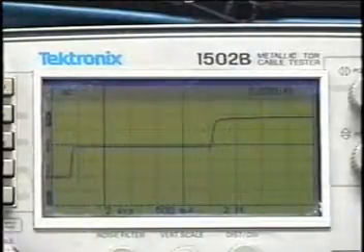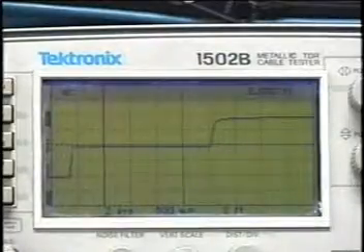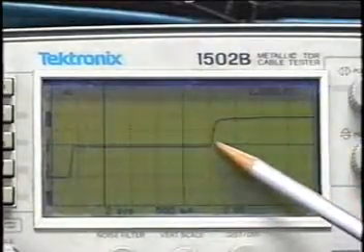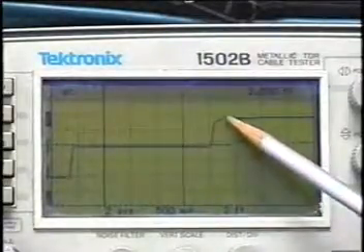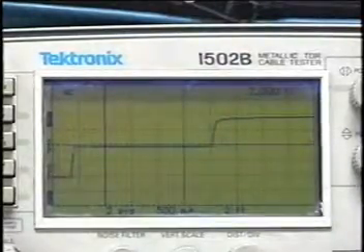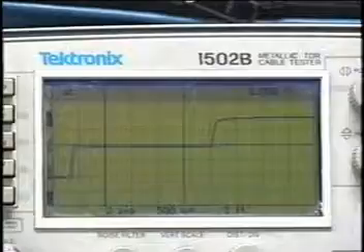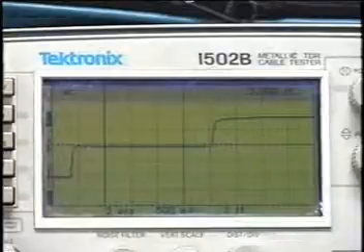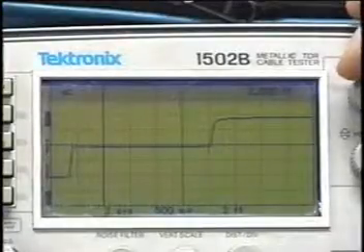The first indication on the left of the tester screen is a test signal, or pulse, being sent down the cable. This test pulse is shown as a rise followed by a horizontal line across the screen. The next point where this horizontal line shows a rise or fall indicates a reflection of the test pulse. This reflection can be caused either by a fault in the cable or by the test pulse reaching the end of the cable. Since every test will show a reflection, whether the cable is good or bad, knowing the length of the cable you are testing will give you an idea of whether the reflected pulse indicates a fault within the cable or simply the termination of the cable.